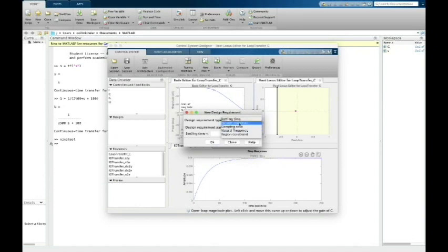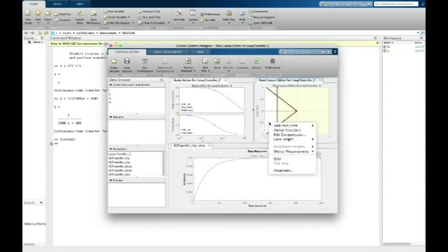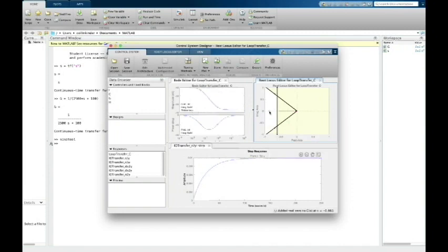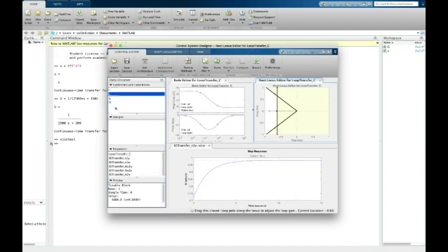In order to get a phase margin such that we could determine the maximum time delay our system could handle, we then added a real left-hand plane pole to the root locus. We began shifting our open loop pole, real zero, and real pole around until we minimized our gains, had a stable closed loop system, and had a reasonable phase margin. This phase margin ended up being 83.5 degrees, and we can have a maximum time delay of 1.41 seconds.